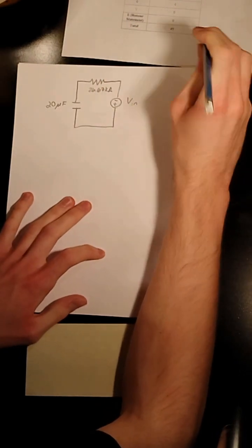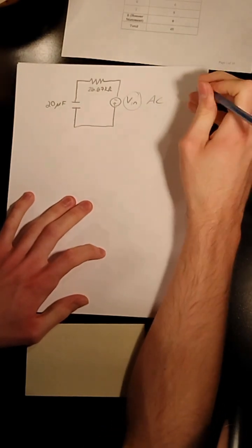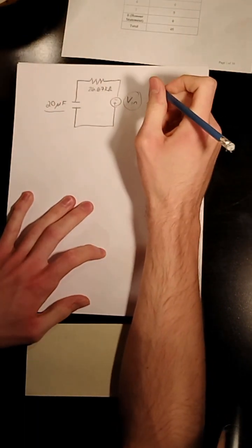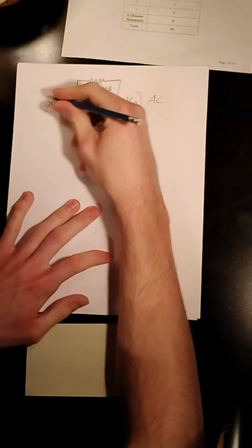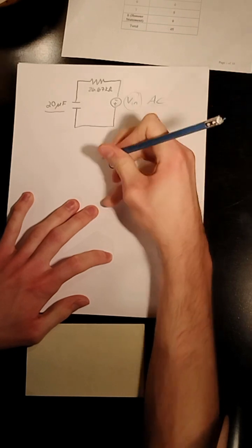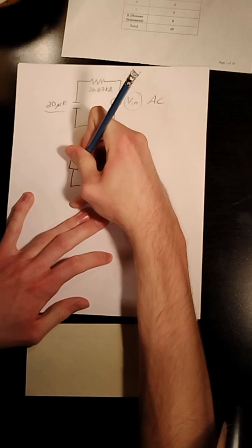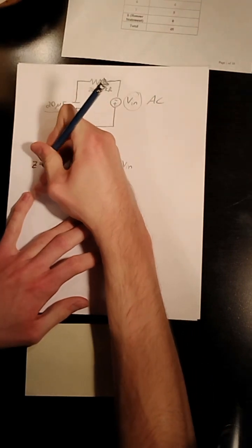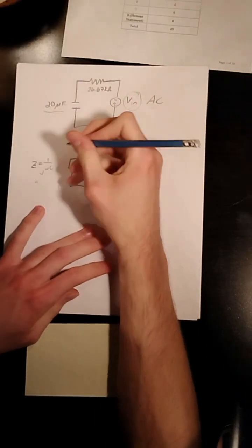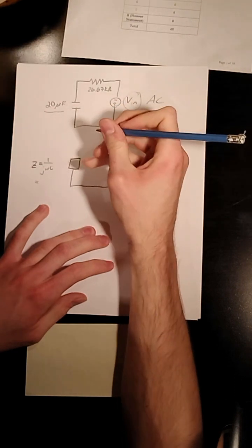And so we know that if Vin becomes an AC, then we can find the reactance or complex impedance of the capacitor. So we can redraw this as Vin, and then this will have resistance of 1 by j omega c, which, well, I guess I can plug it in.